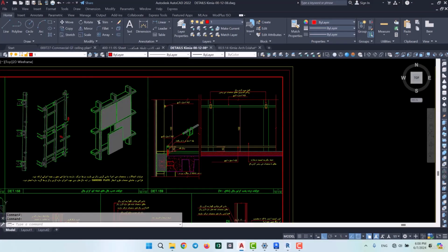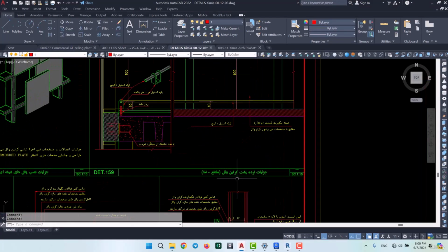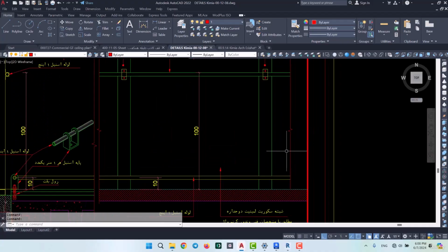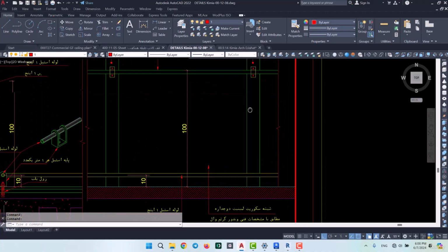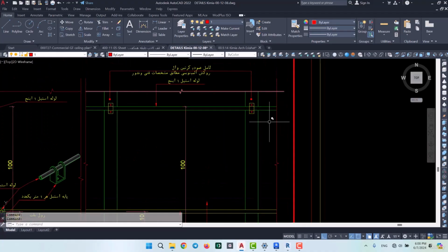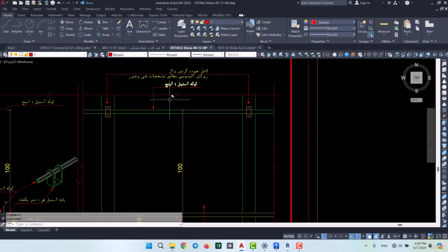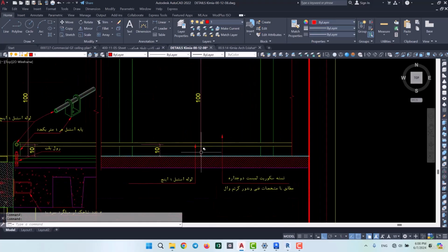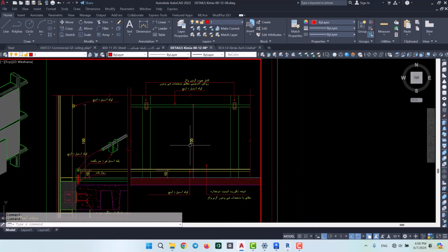And here it is. You can also see it's titled, The Details of the Railings Behind the Curtain Walls, of which we've got the section view or profile in the elevation. Now according to what we see in this elevation, the first thing we notice is that these are the mullions of the curtain walls, these green lines, and above that it says we've got a 1-inch diameter steel pipe, and we've got the same thing going on at the bottom where we need another steel pipe. So basically our railing consists of 2 steel profiles, or maybe it would be better to say that there's one profile only in 2 different elevations.